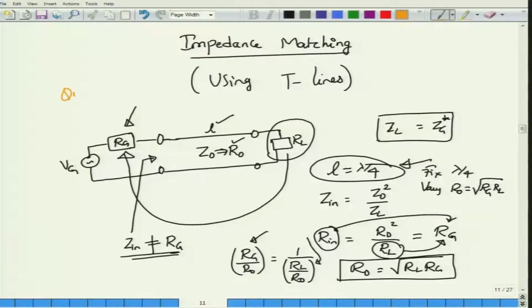So let us write this down. This is the quarter wave transformer or QWT. You might object to this quarter wave transformer because no load will usually be completely resistive, and it would be equal to Zg as well. So there is a version in which you can also replace RL by ZL and Rg by Zg, but that is not very important for us to go into now.